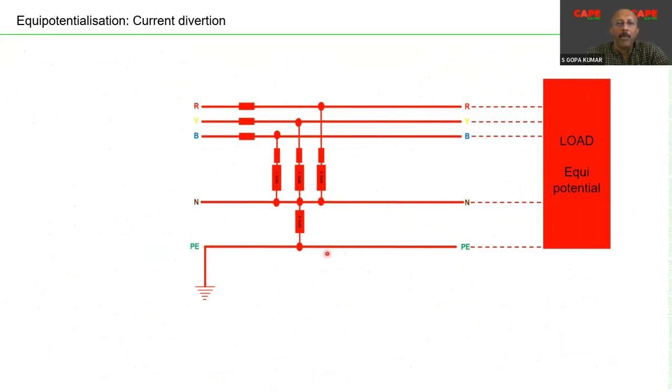But for example, if the earth wire is not running parallel, or if the earth wire is running through a different route, and if there are large loops in the secondary side downstream of the SPD, of course, your equipment is not really protected. You need to have devices closer to the equipment as well.